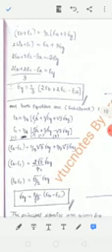Again you simplify, and you will get 1 by 2 of epsilon x plus 3 epsilon y. Put epsilon x equal to epsilon A, which you already know. Now you can substitute, and after substituting, simplify again. You will get epsilon y equal to 1 by 3 of 2 epsilon B plus 2 epsilon C minus epsilon A. We want to determine epsilon x, epsilon y and gamma xy. First we added both equations and got epsilon y.